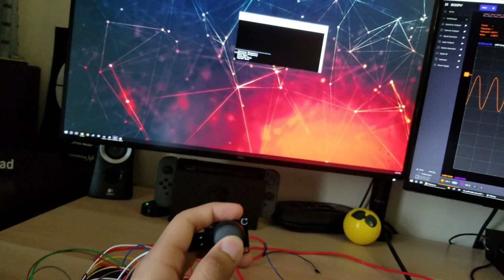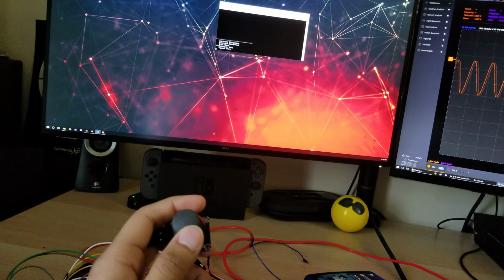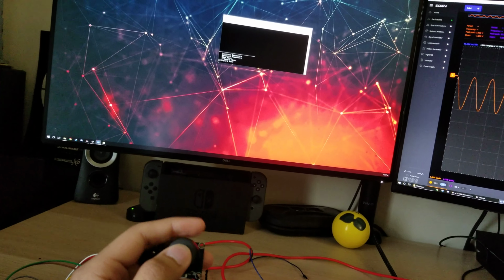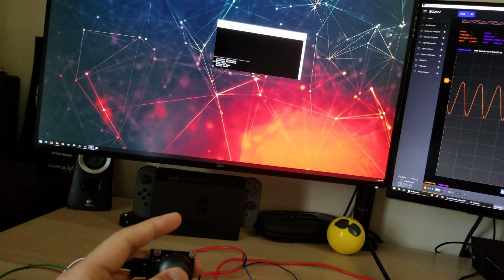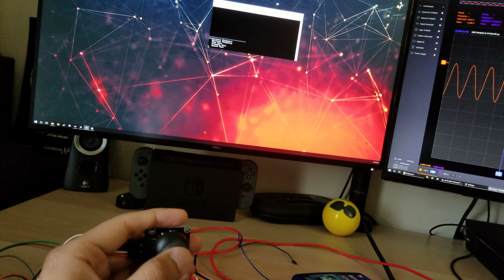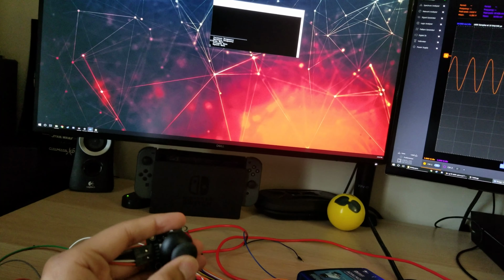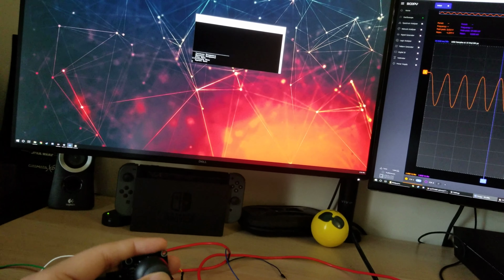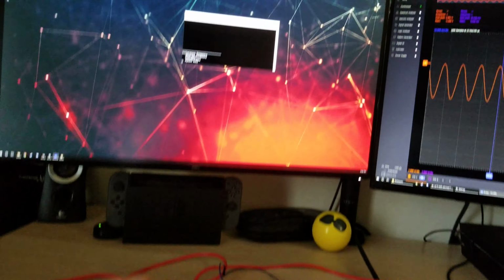It might be a little hard to see, but you can kind of make it out in the background: moving the joystick up and down moves the cursor appropriately on the UART terminal. Basically what I'm doing here is clearing the screen every time I witness a good ADC event, and then reprinting the whole command menu.